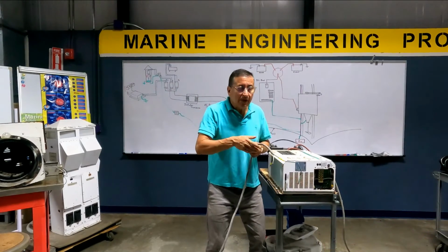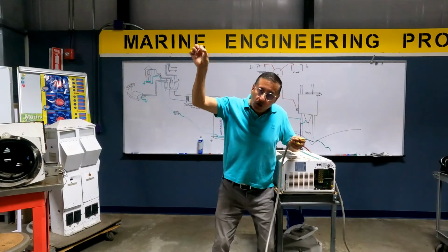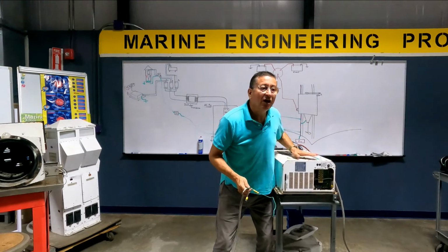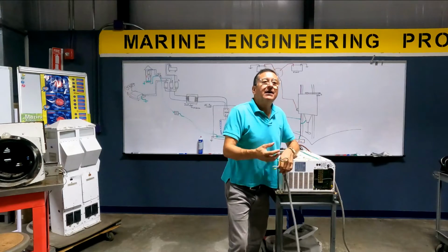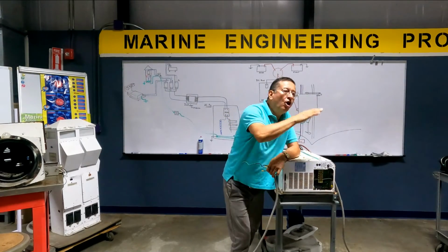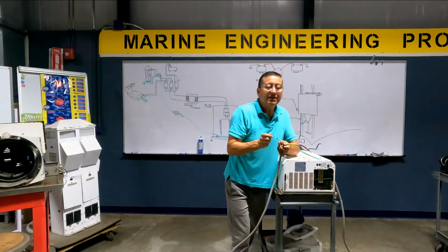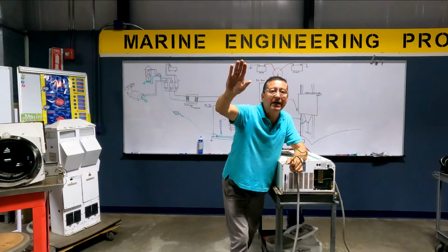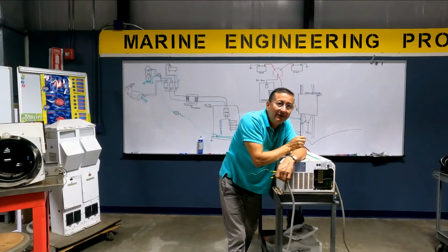After that, one cable goes, white color, neutral, to feed the neutral bus bar in the panel, and another cable from the housing of the equipment goes green color, separated. Listen to me. Only here, neutral and ground are together. After that, both cables travel differently and will never be connected together again. Only at the source of the power. Anybody follow me? Yes, sir.